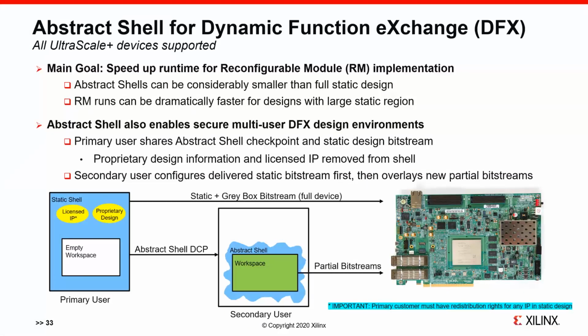Under the DFX section, Abstract Shell for UltraScale Plus devices is in production in 2020.2. This is an advanced technology that works on top of Dynamic Function Exchange and helps to drastically improve the implementation runtime of child configurations in a DFX design.